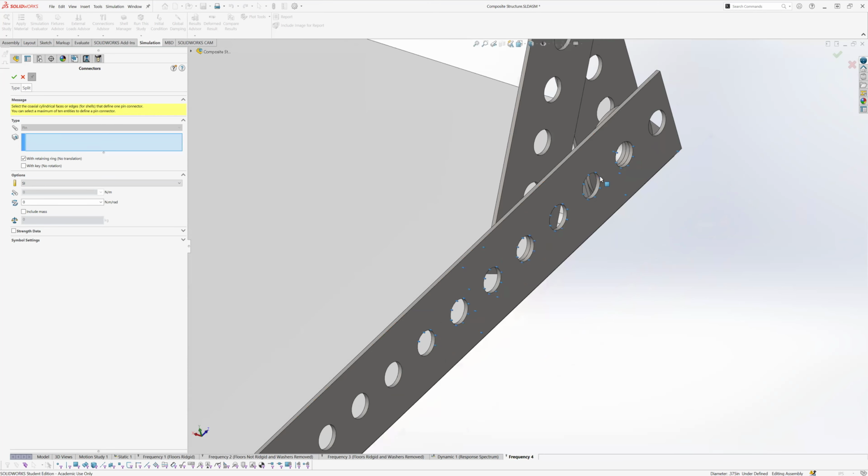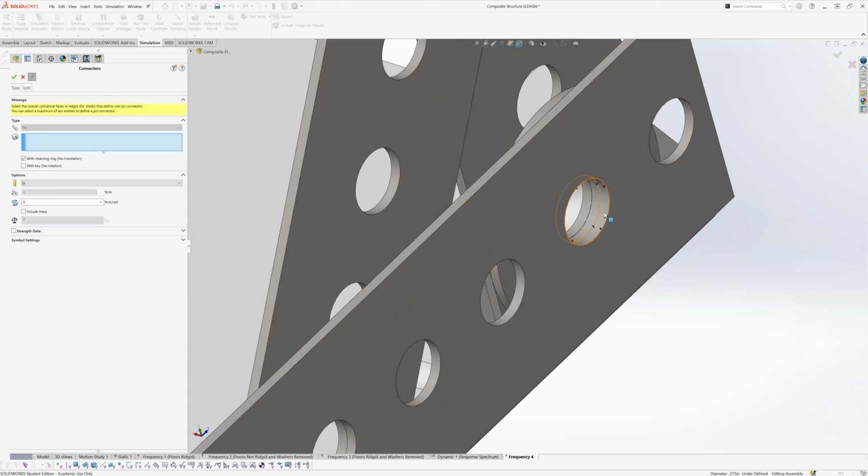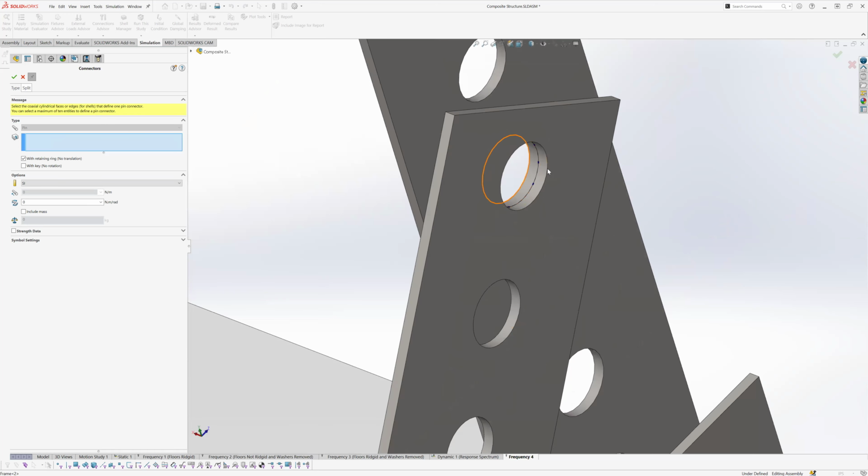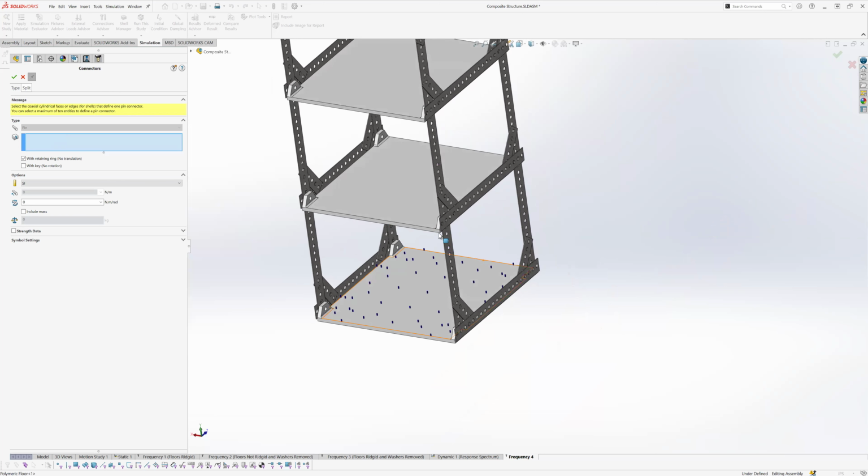We'll try to go through this as quickly as possible, because you probably don't want to see the same thing done 500 times. It's actually not that bad, but it feels that way. So we'll do those, and that should be this entire level here. Now I'll unpin and then hit the red X, which means I'm not adding any more. If I hit the green check, it's going to give me an error because I don't have any faces selected.